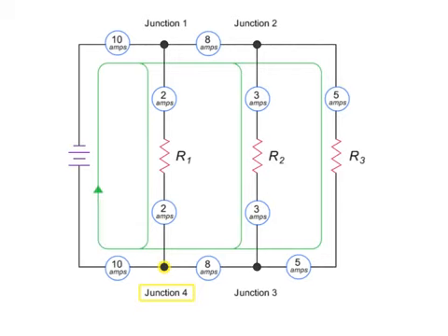An important difference in a parallel circuit is that voltage is the same throughout the circuit, so using a voltmeter to measure volts at each load will yield voltage readings equal to that at the source.